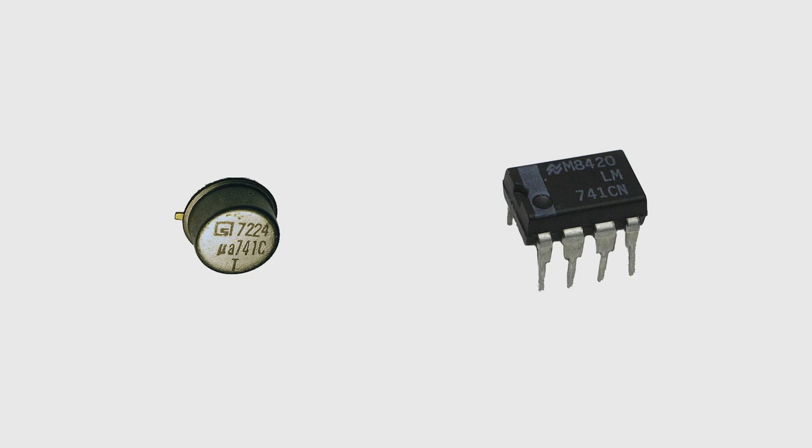But it's essentially the same amplifier. So many circuits were built with these. There are better op amps around now. This was one of the earlier ones. But that is one of the basic building blocks of just about anything analog, because it's such an elegant design. It's very simple. There's only like 8 legs on the thing. And we looked earlier at what you had: a negative and positive input, negative and positive voltage, an output, and a ground. So what do you think is in that 741?